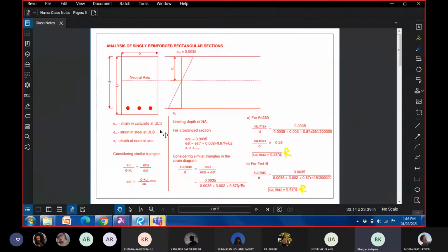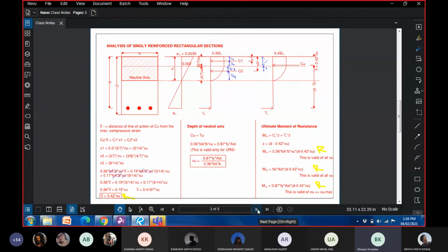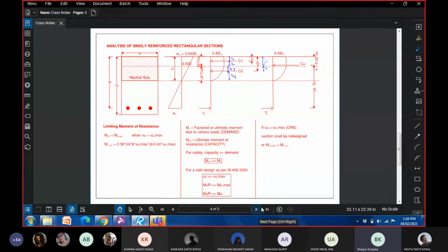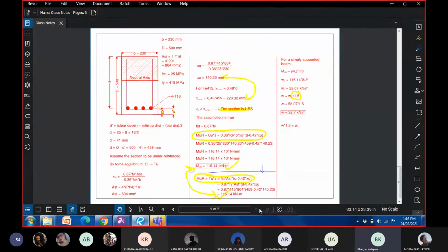Okay, so in the last few sessions, we talked about singly reinforced beam, wherein we provide reinforcement only on the tension side. In the last lecture, particularly, we learned about the analysis of singly reinforced beam, meaning that we know the dimensions of the beam, the amount of reinforcement, and then we back calculate the moment that it can carry, and hence the amount of load that we can put on the beam. And we just solved one numerical pertaining to under reinforced beams, and we saw how we use all the equations and all the formulations that we studied, and how we put them in actual practice.